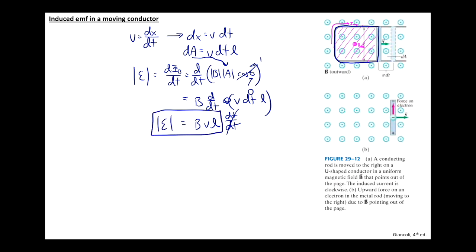And take a look at what's left. The induced voltage there is given by the field that's being generated by something else, times how long the bar is that's moving, times how fast it's moving, okay? So if you think about it, there's nothing in that equation that really talks about the rest of this loop. There's nothing there that's left at all. Instead, everything that's there has to do with this piece of metal and the magnetic field that it's passing over,